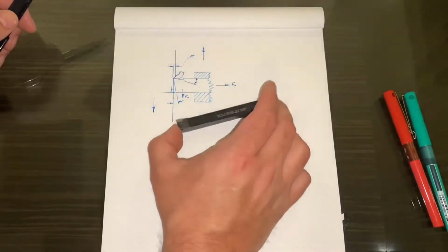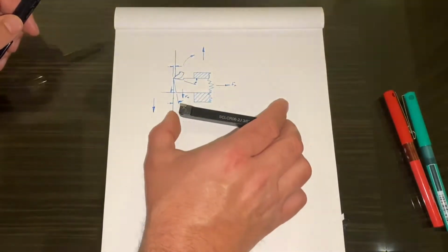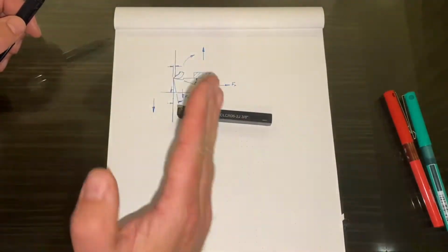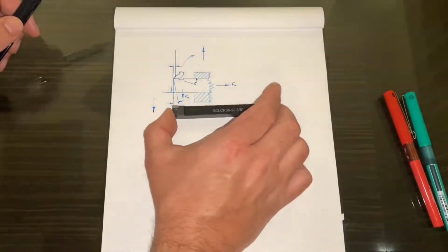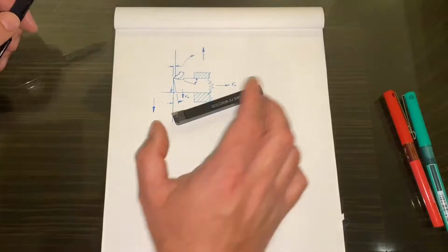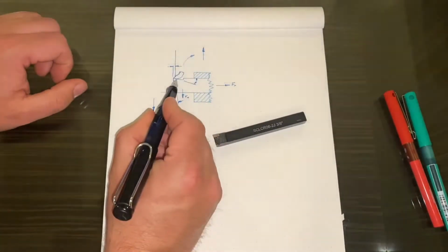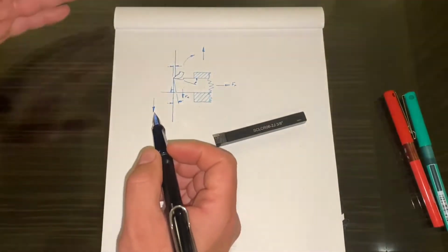So when it's in that orientation, then you can see that the cutting tip is pulled away from the work, and the relief angle now contacts the workpiece. If we tilt it that way, then what happens is we reduce this rake angle and we put what's called either neutral or negative rake.